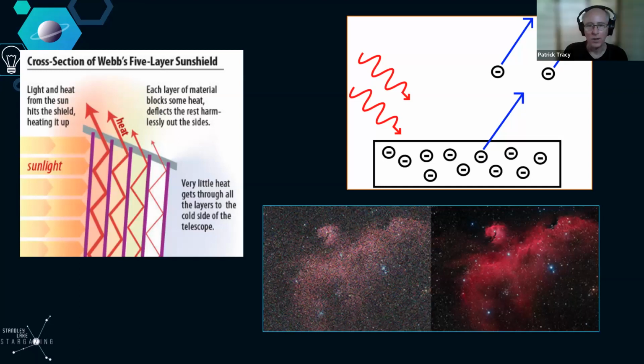Slightly nerdy question. Do you know anything about the difference between CCD and CMOS cameras in this application? That is an extremely nerdy question, and I love it. There are different properties. They respond differently in the infrared and the visible wavelengths. My understanding is that the CCDs are significantly more responsive to infrared wavelengths. The very first consideration you have to make for any detector is what material you're going to be making it out of.